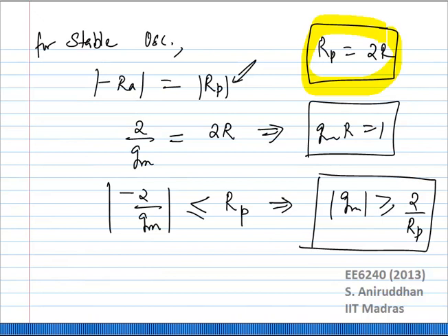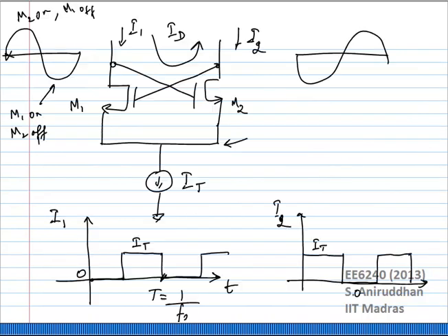Okay, so now we looked at all the startup conditions. The next step was to actually look at what the amplitude will look like, and to do that we tried to create a large signal model equivalent circuit of the cross coupled pair, because at the end of the day the cross coupled pair is modulating the bias current somehow and pumping it into the RLC tank, right? You figure out what that current is and multiply it by the impedance of the RLC tank, you will get the output amplitude. That is the easiest way to do this.